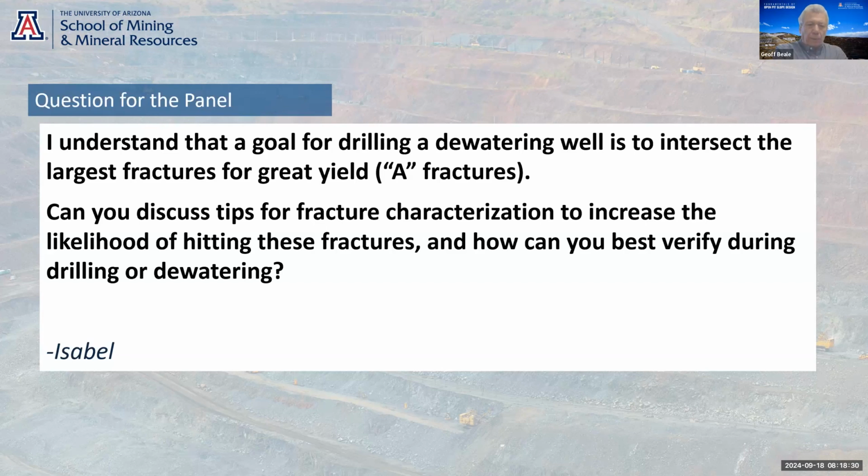And really, for the second part, there's no substitute for drilling a pilot hole, particularly if you're going to have to spend a lot of money on a production well. So you can look at the fractures from core, you can look at the fracture orientations from core logging, from the general understanding of the site, but there's no substitute for drilling a pilot hole and testing the fractures that you encounter.